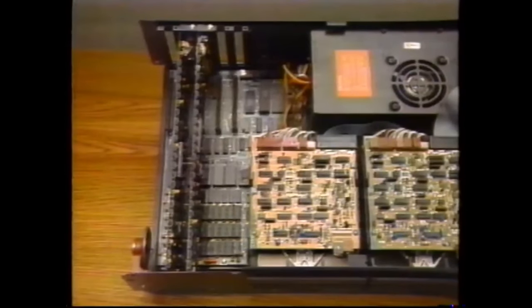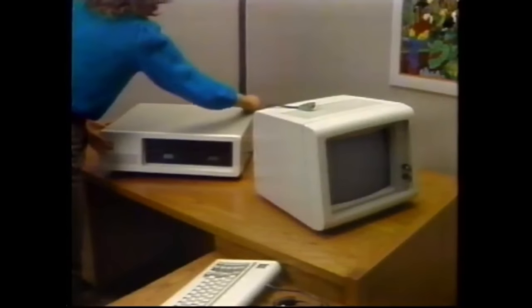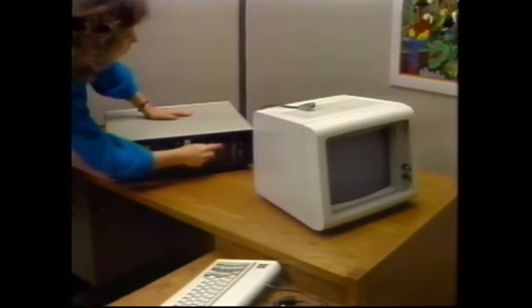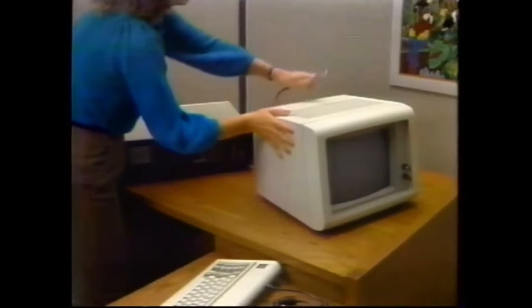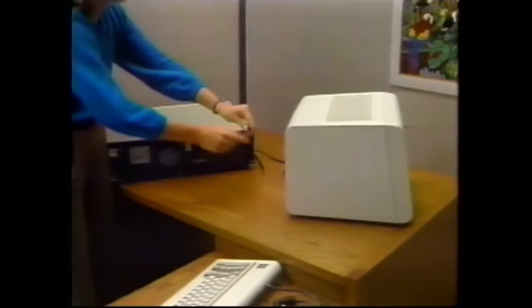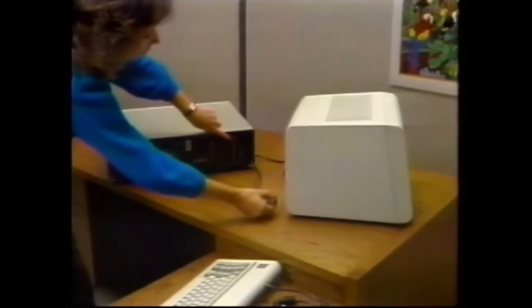In this computer, we have an IBM monochrome display adapter and the IBM color graphics adapter in their respective slots. Turn your computer around so you can work on the back panel where the connectors are. Now, find the video cable that comes with your IBM video monitor. It'll be the cable that has connectors enclosed in a frame like a D on both ends. If you look carefully, you can count 9 pinholes inside of the D-shaped enclosure.